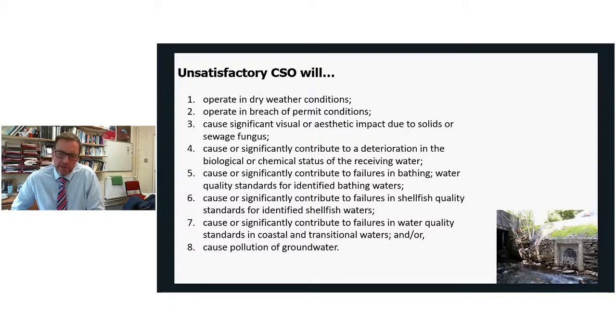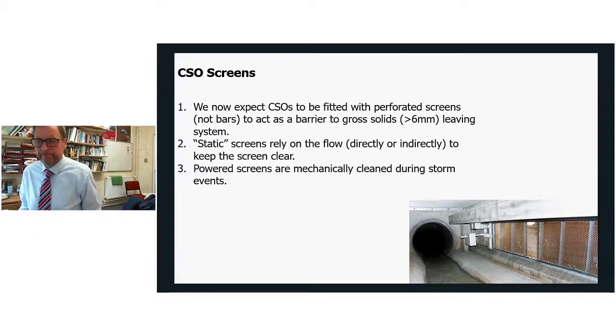Shellfish quality, again, water quality standards, and causing pollution to groundwater. So all these things are logical things, and it's these things that trigger some of the investment we've seen in CSO removal or mitigation. We now expect CSOs to be fitted with perforated screens. So not just the bars we see in the pictures, but normally it's recognised that perforated screens are the best way of retaining solids greater than 6 millimetres.